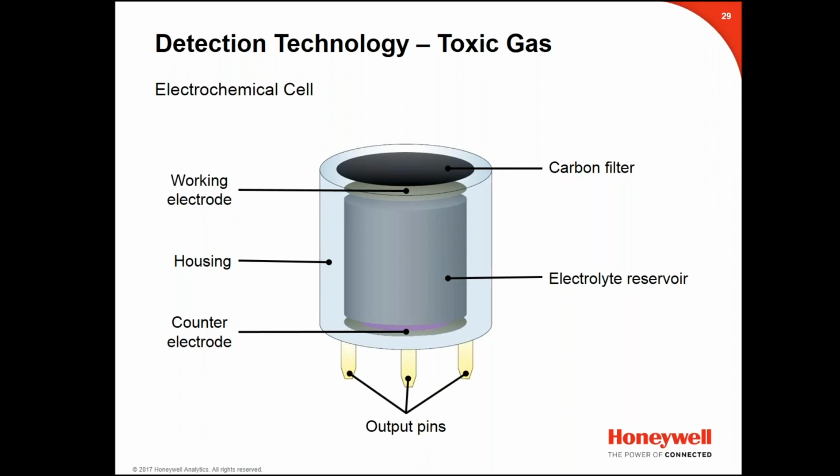Okay. Next question we have is, I'm assuming it's an electrochemical sensor, does it eventually get full of the sensing gas? No. So when we have the migration, it's simply a single molecule at a time. As the molecule enters the electrolyte reservoir, one molecule portion of that reservoir gets consumed because we have the transfer of current between the counter and the working electrode. So we're not worried about the electrochemical cell filling up with gas as much as we are with